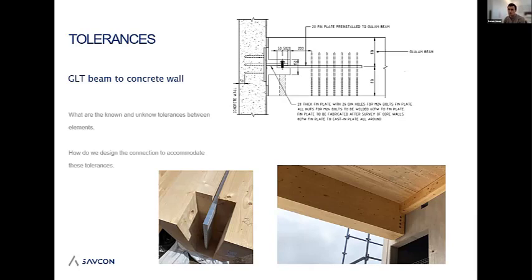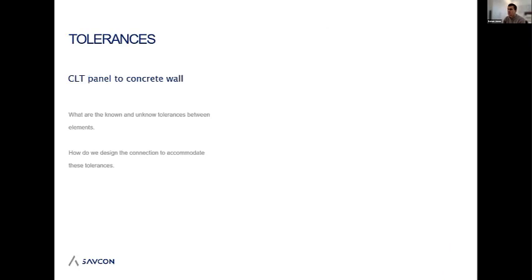It might only be 2 weeks prior to us installing this beam. So the way that we did that is that we had that on-site weld. So we went there, we cast in the cast-in plates, which can be out of tolerance in an up, down, left to right, or even out of pitch direction. We cast that in, had a survey mark, and then custom made that thin plate and welded it on site. That took all those tolerances out. So on both the negative case and also the positive case, so on one side of the core and the other side of the core, that took up those tolerances. That's quite a tough detail to get right, but a very successful connection.